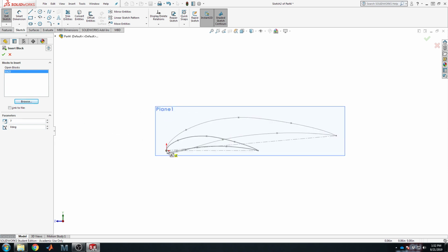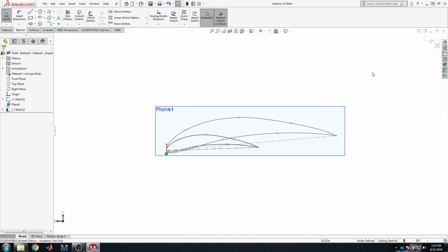So this wing doesn't make much sense. It'd have wash in, so the root would actually be at a lower angle than the tip. So let's prepare the tip of the wing to have a little bit of washout. Okay. Place this with 0 leading edge sweep. The trailing edge will actually come forward. So this will be technically a forward swept wing. Kind of goofy, but neat. And go ahead and leave that sketch.